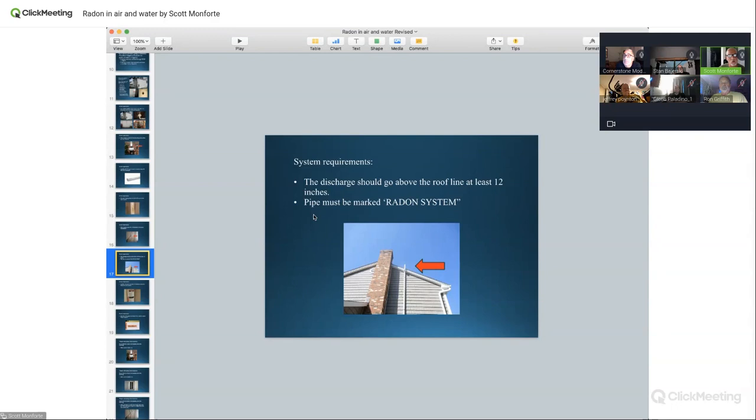Okay. So if you use a lower roof on a colonial, and I think there's a picture in here, let me see. If the pipe is coming, if it looks like it's here, you're good. But here's another, I'm going to throw this at you. We'll just use this picture. See where that gable vent is? Now, technically, the attic, the house is stack effect, up, out, you're okay. But there are times where the pipe is very close to the gable vent. It's not the worst case scenario.